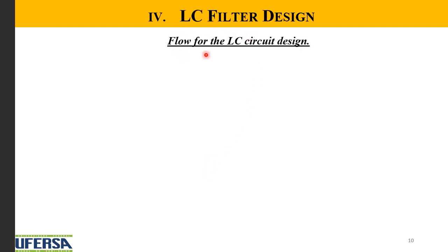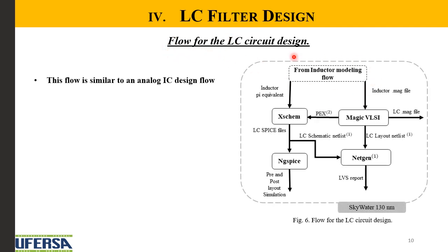So about the LC filter, we proposed this flow. This flow is similar to an analog IC design flow. We have the inductor pi equivalent in Xschem plus ngSpice to run the pre and post layout simulations. There is Magic to create the layout and run the PEX, and Netgen to run the LVS, layout versus schematic.